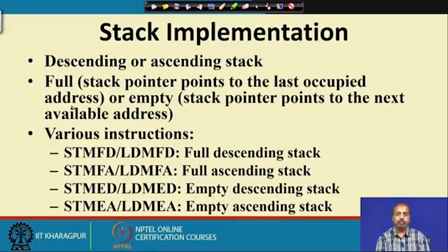So, we can have any variant. You should not mix up these instructions. If you have used STMFD for storing the values onto the stack, then while loading you should not use LDMFA, because then the values that you get will be corrupted. Otherwise there is no problem. If you are using the pair properly, then there is no problem, and you will get the same values popped out from the stack.